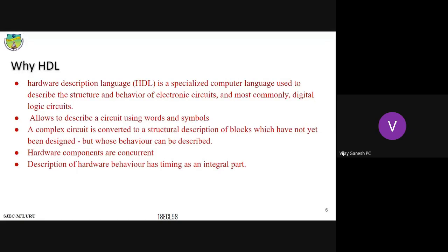Whereas the hardware description language focuses on that. When I say plus, it asks what kind of adder I have to use. From the top level design, I just say a plus symbol, that's all. In digital design, if I want to design an adder, we all know for a 1-bit adder, the sum expression is given as A XOR B XOR Cin. So the plus sign should be converted into the digital circuit. If I want to do that, then I require a hardware description language. Okay, that's the first thing.